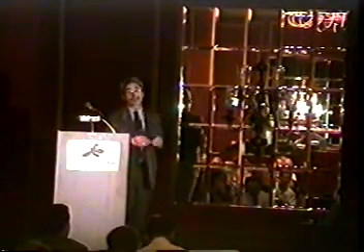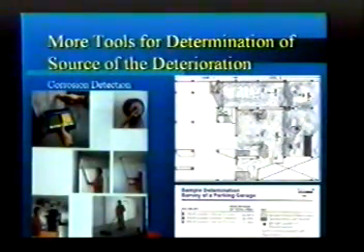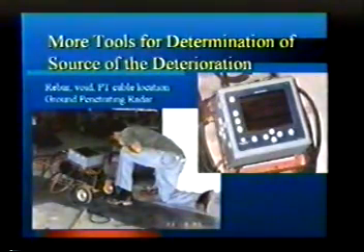A couple others. How much corrosion is really going on inside of this concrete that has not yet delaminated? We have a half-cell study. Corrosion is only a battery operation. So if we put a big voltmeter on it, we can read the voltage. Once we read the voltage, we can get contour signs around the rebar where you're most active. So we can get a prediction of the future. Okay, it hasn't delaminated today, but maybe it will delaminate in the future. This is also one of our exhibitors here, has this type of device, as well as there's others. All right, a couple other slick tools.